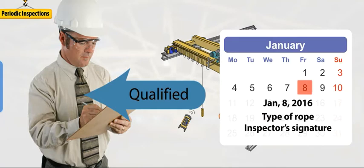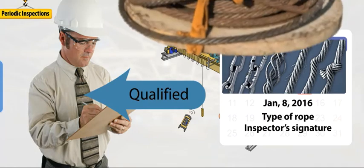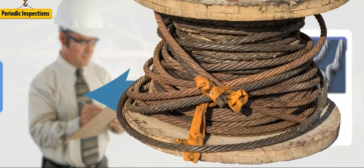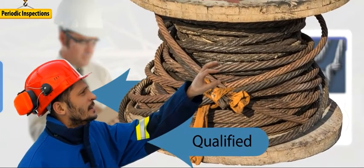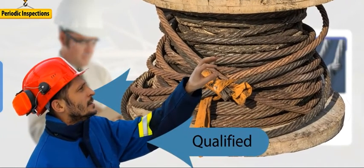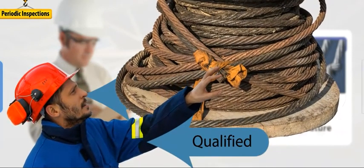Rope inspection should look for unsafe conditions such as corrosion, worn or broken outside wires, loss of diameter, connections that are cracked, bent, or worn, and severe kinking, crushing, or unraveling. Close attention must be paid to areas where rope contacts sheaves, saddles, or limited rope travel areas. If a piece of rope hasn't been used in over a month, a qualified person must inspect it before it can be used. Generally, periodic inspections are not the responsibility of operators, but might be done either by your company's maintenance crew or outside contractors who specialize in crane inspection.